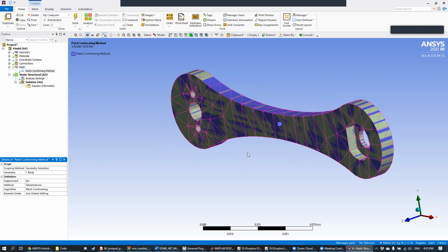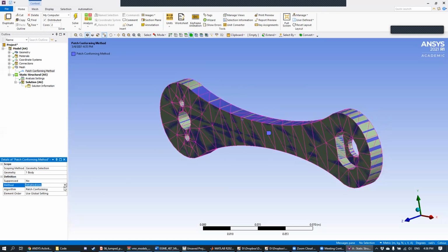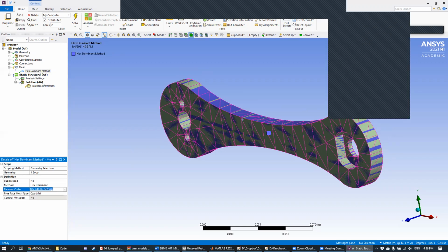But the thing with tetrahedrons is that because a four-sided pyramid is not as space filling as a brick, what tends to happen is that you end up with a lot of elements, and sometimes that's a consideration. It depends on the constraints of your geometry too. We'll talk about this a lot more later in the class once we start getting to the practical finite element stuff. But just to show you a difference, I'm going to pick hexes for this. Okay, let me check the chat real quick.